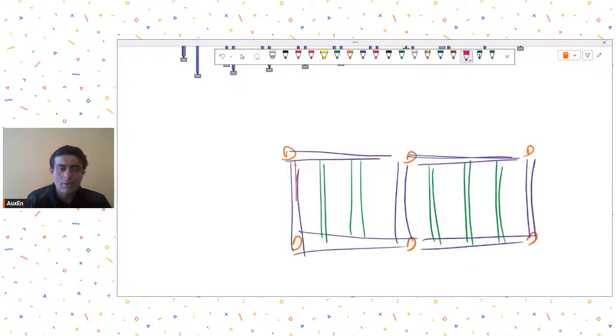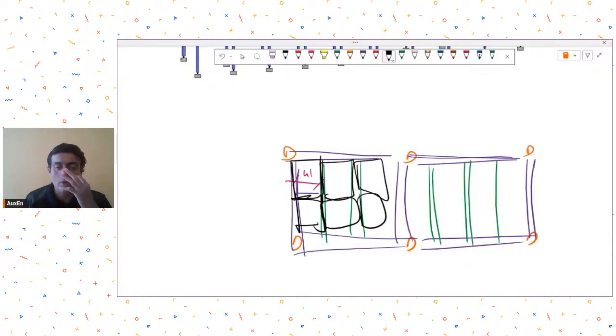So I'm assuming that this dimension is 4 feet and the puff panel is supported along the shorter span. You also need to know how the puff panel is going to be supported. Is it supported along the shorter span, or on all four edges? That information also you need to know. Once you note these inputs, then you will be able to finalize the framing.